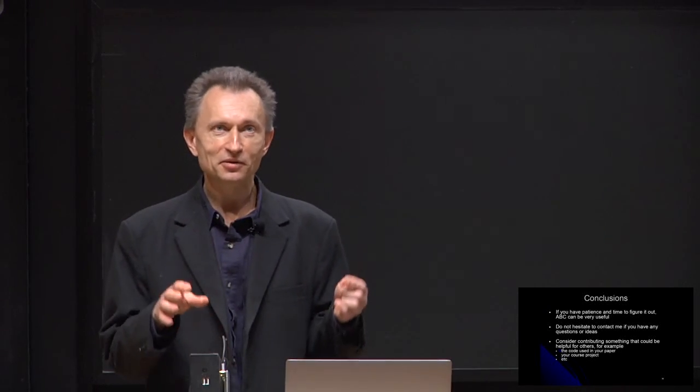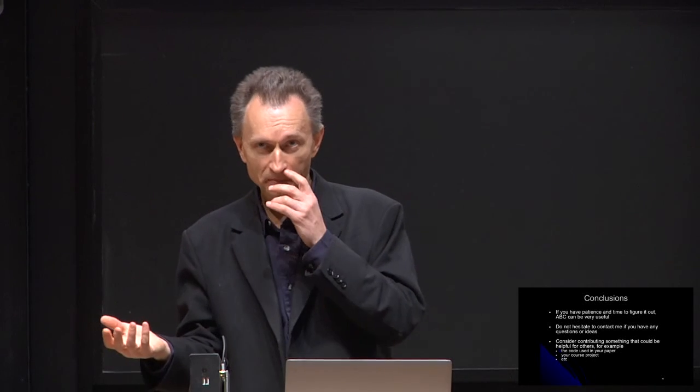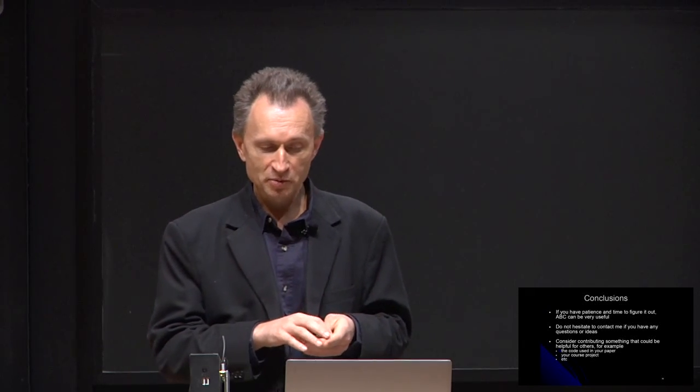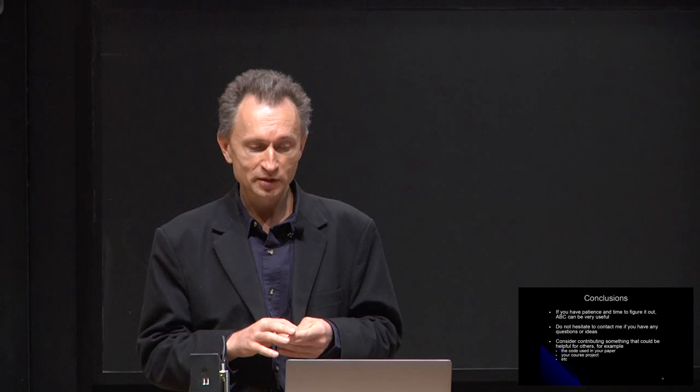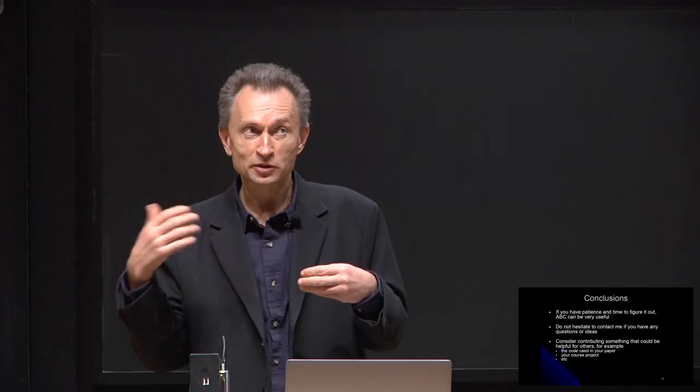Yes, so there are many optimization use cases. In one of them, you will take your logic, whatever it is, flatten it into an AIG, optimize the AIG very hard, and then remap it into your library. Another optimization would be to keep your mapping as much as we can, and then locally optimize it, doing some kind of post-mapping resynthesis. So ABC has both ways of working with designs, and it actually depends on your preference, depends on your runtime budget, depends on how much improvement you expect, and how important it is to preserve your current mapping.